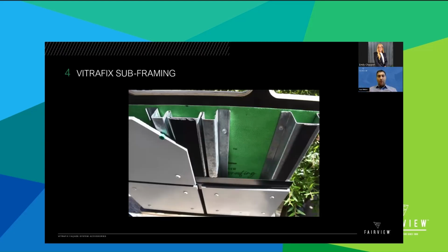Moving forward, in our wall build-up, we'll leave the sarking behind, the back wall, and we now enter the cavity. The cavity, as we saw before, is very important, which is where all the moisture, all the condensation is kept and removed. So to support panels, it's also important to have a designed subframe system. Fairview supply Vitrafix profiles, a range of fully component separating accessories. Structural and non-structural elements are available, hand-in-hand with cladding options, in achieving a full wall build-up system solution, tested and compliant.